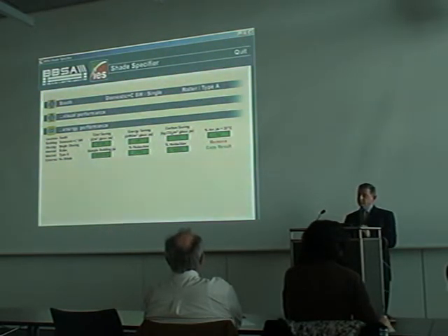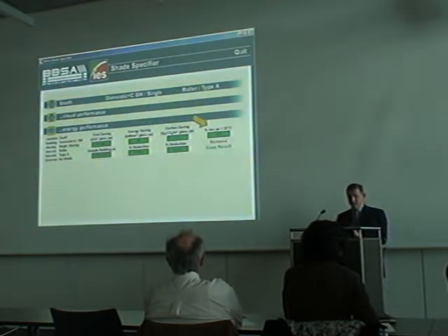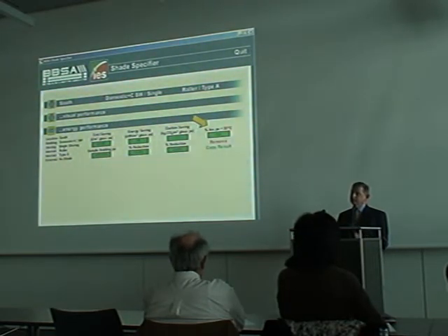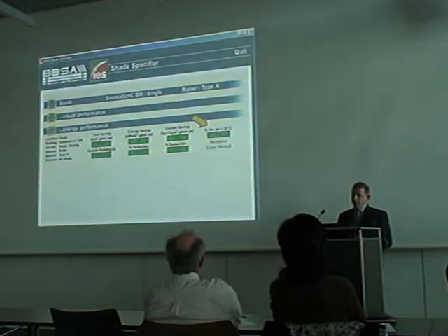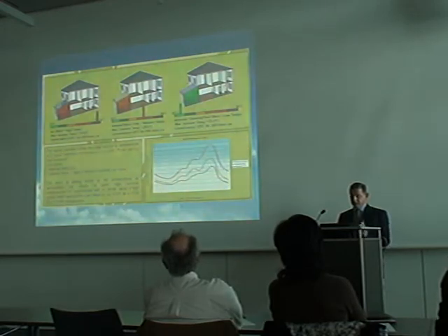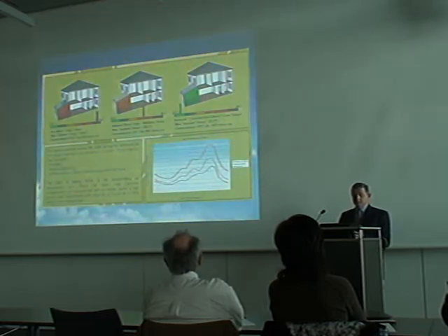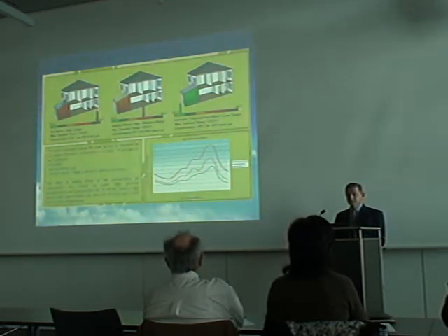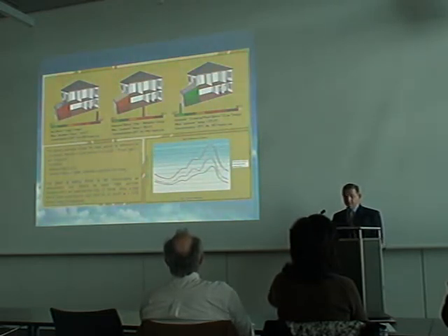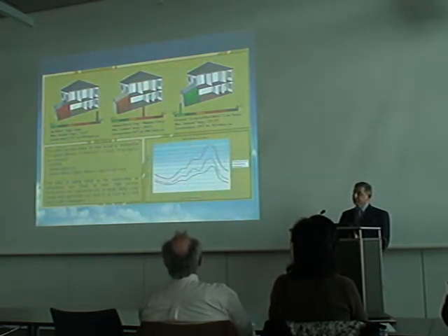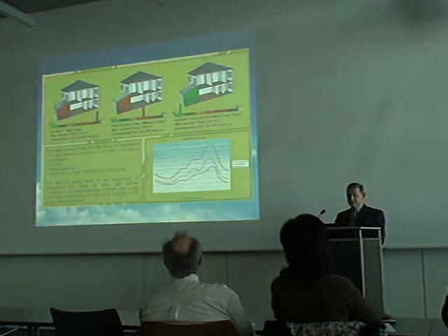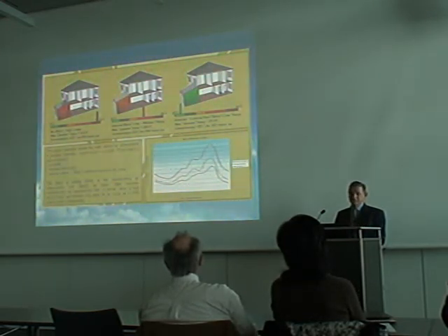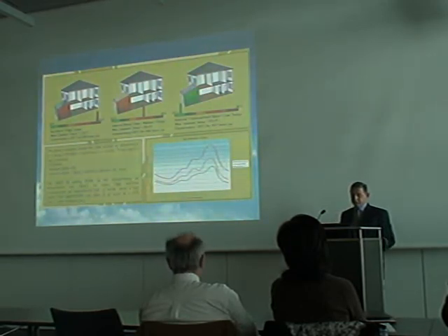But specifically at the moment, the way that we've used this in the UK is to look at the overheating of conservatories, where we can show that by applying correct blinds, a very expensive extension to your home that you've designed and built can actually be shaded more effectively. And this is an example here where we've run some specific modelling which shows without blinds that building, which is in the south of England, would reach a maximum temperature of 36 degrees. It exceeds 25 degrees C, a comfortable environment, for 858 hours a year.